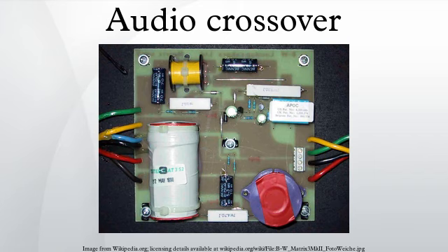Four-way crossovers are not very common in speaker design, primarily due to the complexity involved, which is not generally justified by better acoustic performance. An extra HPF section may be present in an N-way loudspeaker crossover to protect the lowest frequency driver from frequencies lower than it can safely handle. Such a crossover would then have a bandpass filter for the lowest frequency driver. Similarly, the highest frequency driver may have a protective LPF section to prevent high-frequency damage, though this is far less common.